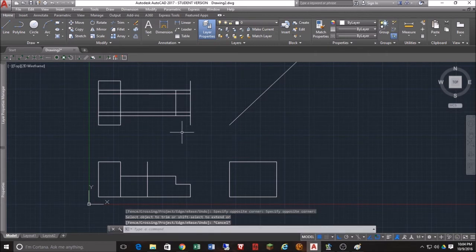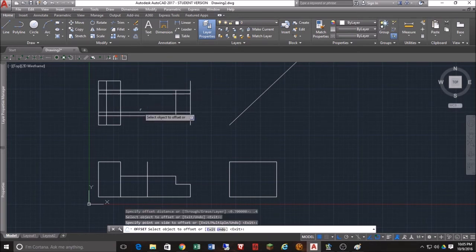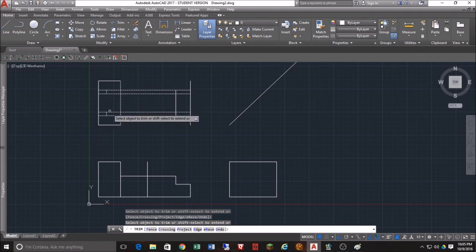Good. Okay. Now, looking at my isometric view here, to finish this part, our shape comes in a little bit this way and then continues on. Well, that notch, where it comes down, is 0.4 from the back side, or from the far left side. So let's offset 0.4 from that side, and that gives us our trimming edge there. So now we can trim that. Let's keep that one there too. And trim here, here, here. Kind of like this.